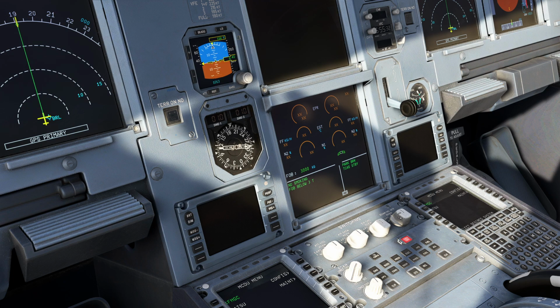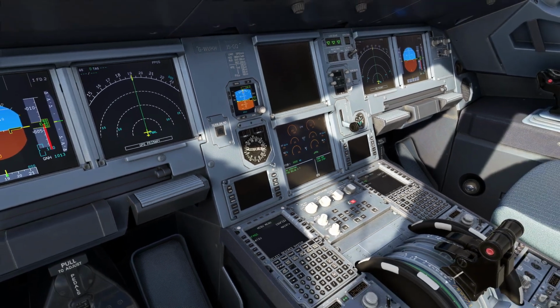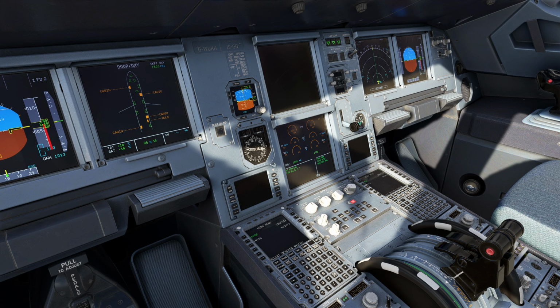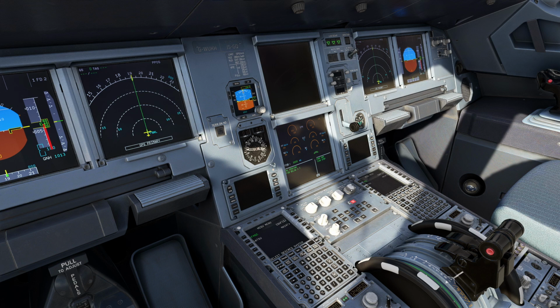which means this switch with that selection to the captain side. You can see the engine warning display remain on system display at the lower part of the ECAM display, and system display, which previously indicated at this area, jumps to the navigation display here by selection of this switch. I return this switch to normal and select it to the first officer side, and you can see the navigation display of the first officer replaced by the system display, which previously located at the lower part of the ECAM display.